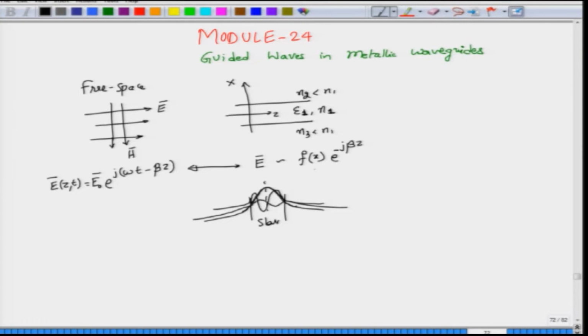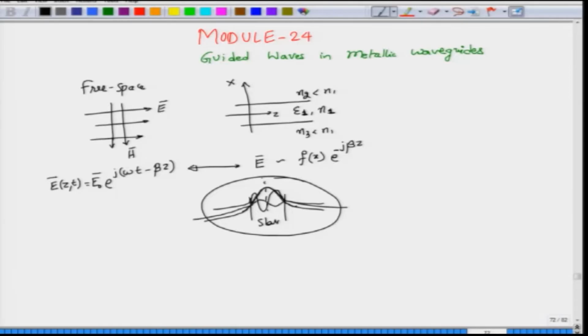So, which clearly indicates that although in terms of the phasor the propagation part along z is the same for both types of modes, this particular mode is more confined in the slab, and outside of this particular slab the energy basically decays rapidly in an exponential form, and this matches our expectation of how a mode or a wave would be guided inside a material, right.